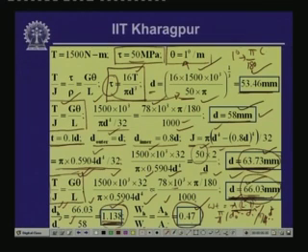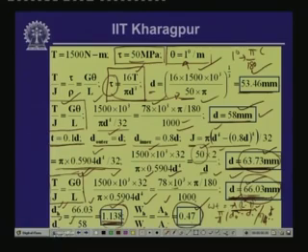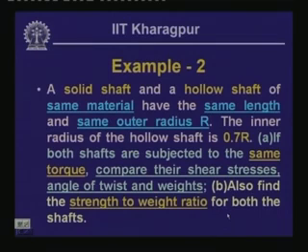So you see that though we are utilizing 14% extra in the diameter, we are gaining in weight, to the tune of half the weight of the solid bar. Evidently, the hollow tube is more efficient than a solid shaft, and this will be more clear if we look into the next problem.